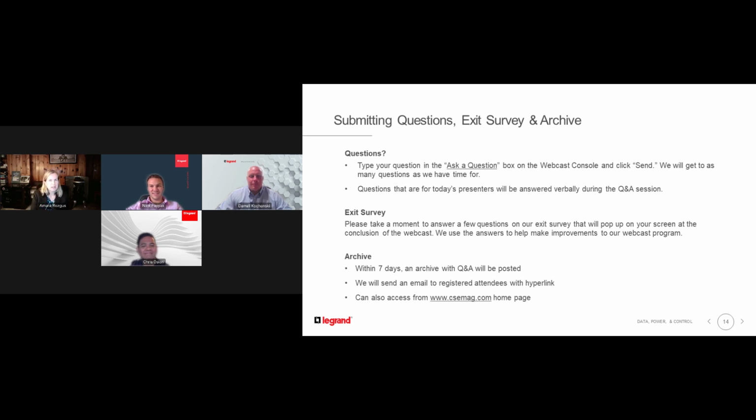All right, Nick, here is a question for you. Are busways field configured, and can you talk more about the reuse of them? Sure. Busways are UL listed, and there are a set of creepage and clearances that we need to abide by. So our recommendation is you cannot configure the busway in the field.